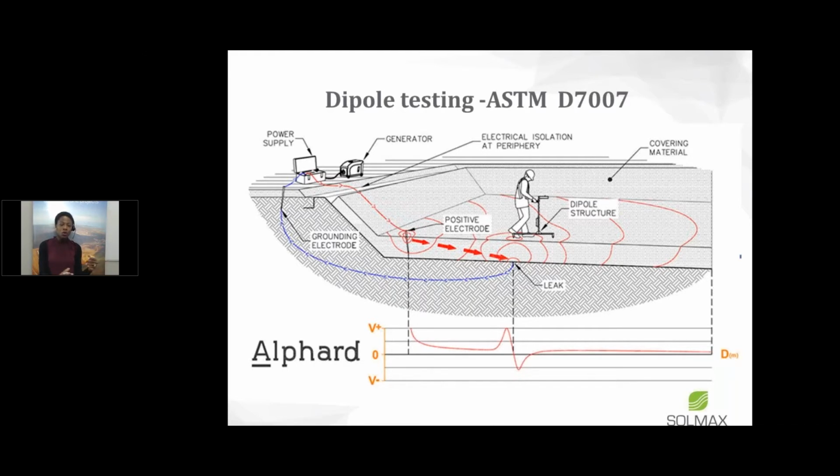So what the technician will rely on in this case is a distinct sine wave. At the bottom there's a graph that shows the sine wave. That's what the technician is looking for. When he gets that signal, he knows there's a leak somewhere, and they can narrow down on that signal and find exactly where that leak is, excavate, and have the leak repaired.